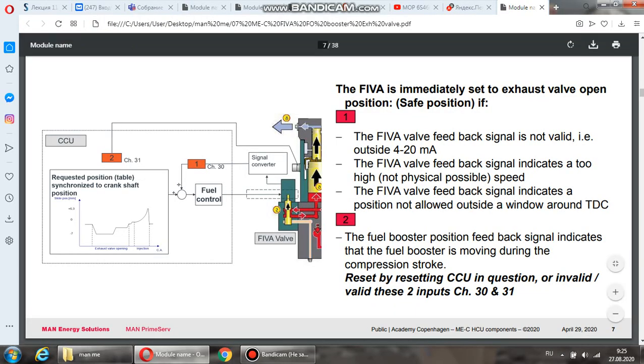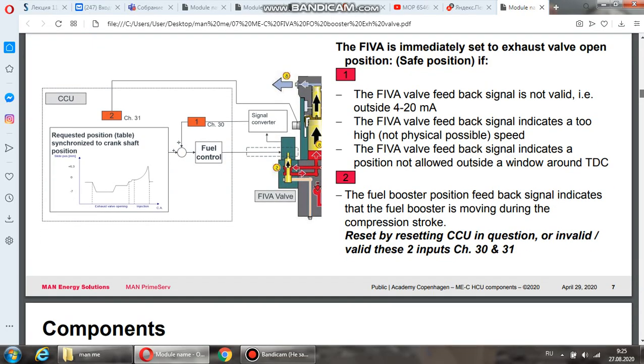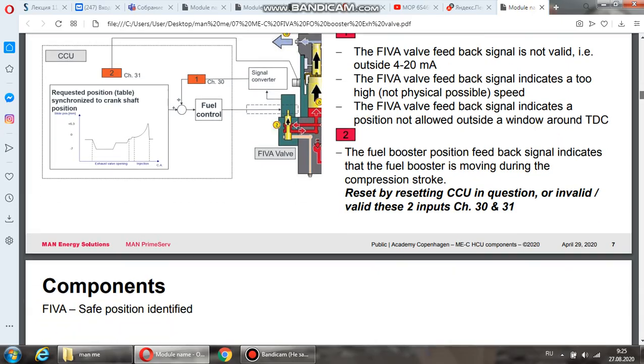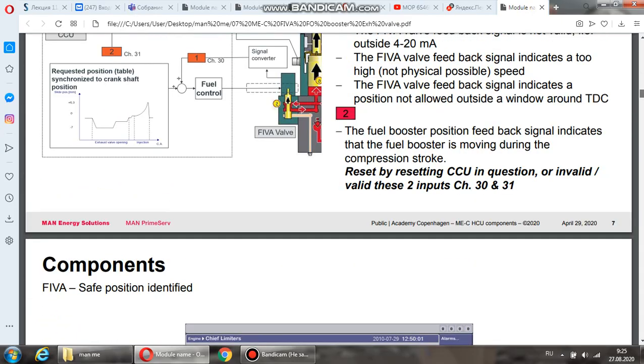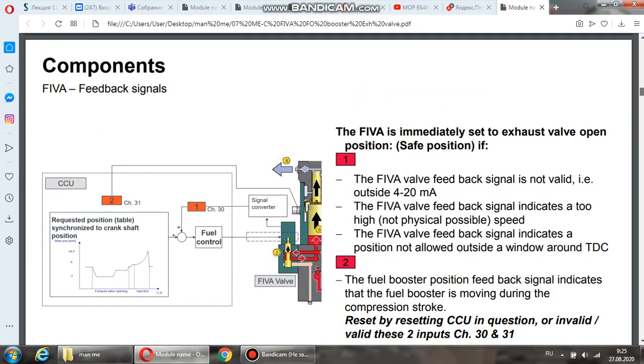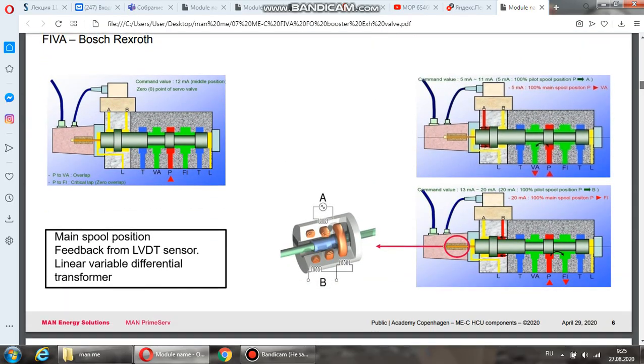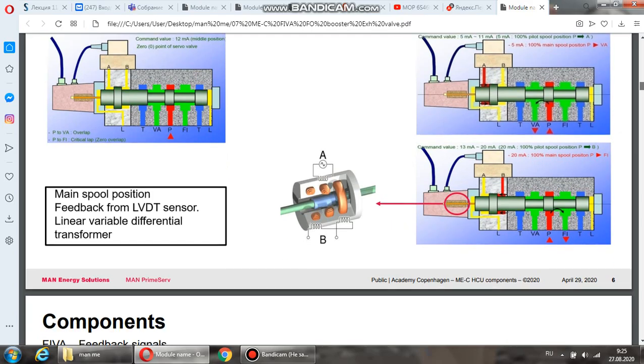The red line is our pressure line. Remember from yesterday, we have control oil pressure on our pilot valve. We have constant oil pressure on the exhaust side, and then we have working pressure in the center here for the movement.